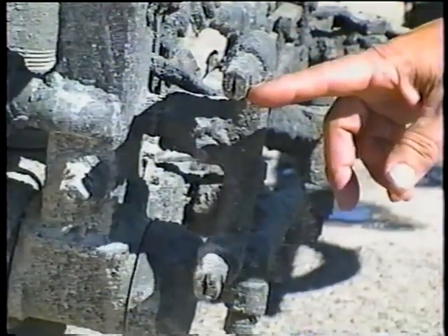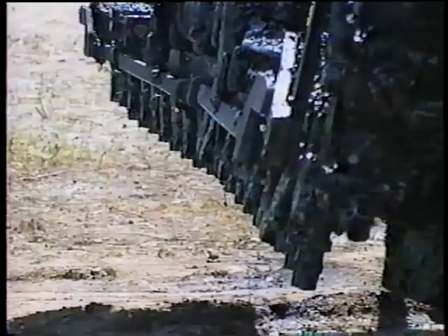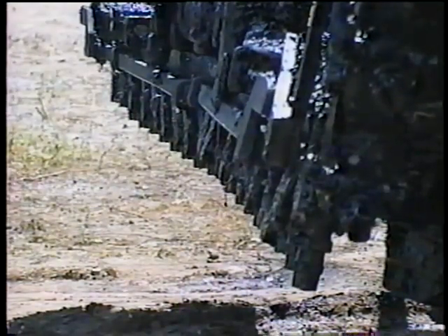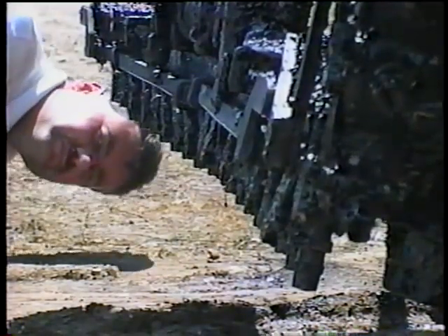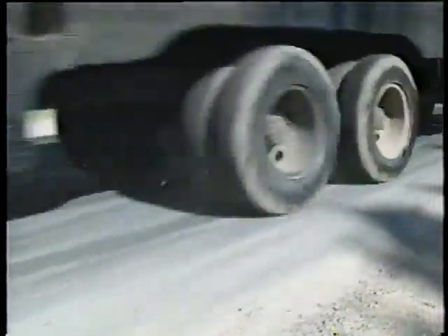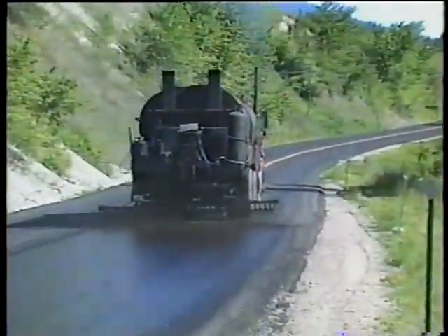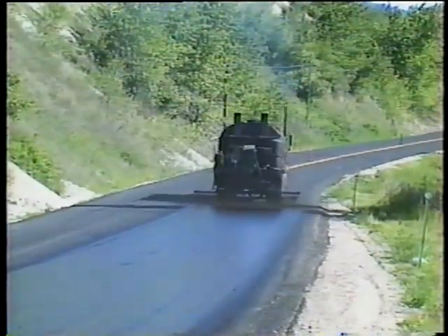Next, look at the spray bar, starting with the nozzles. They all have to be clean and angled in the same direction to get the proper coverage. And check the height of the spray bar. The proper bar height, nozzle angles, and application pressure determine the quality of the tack spray pattern. Generally, you want a double or triple lap coverage. This is a good tack application, smooth, even, and uniform.